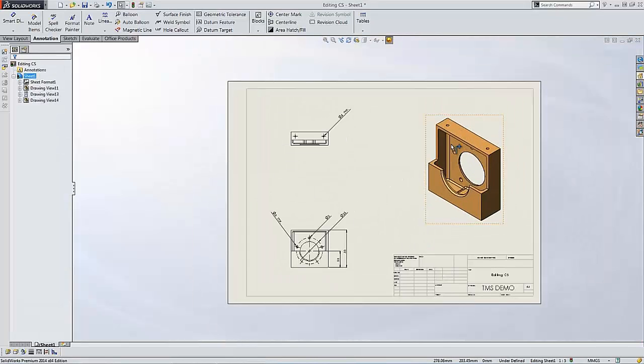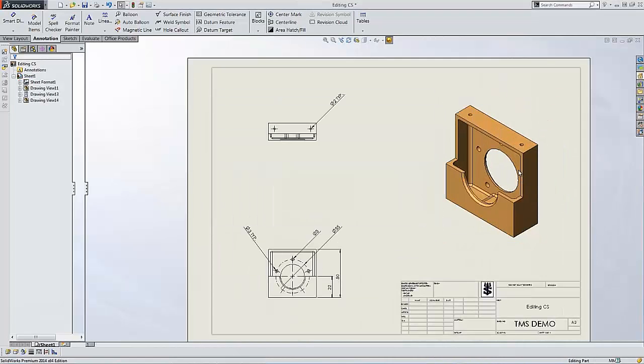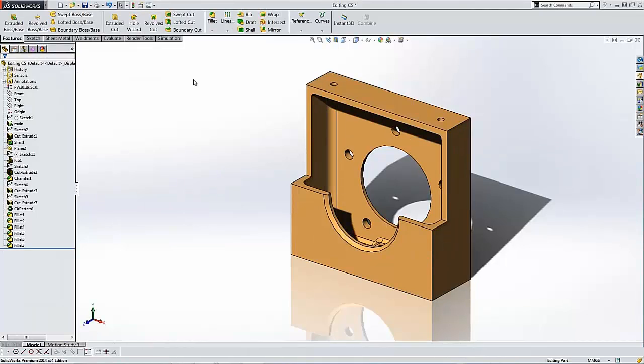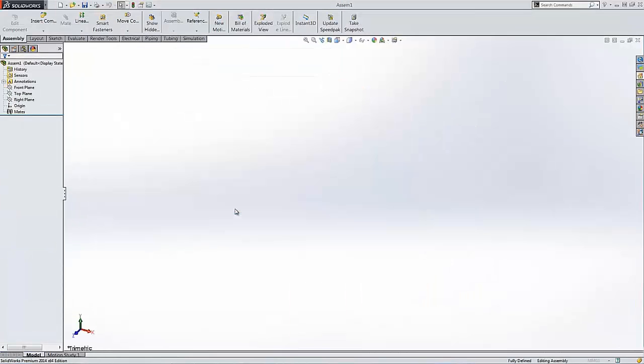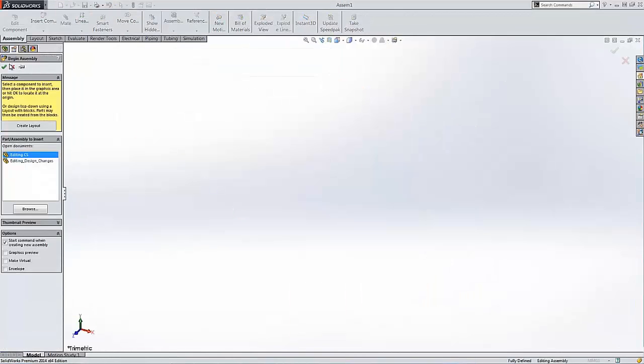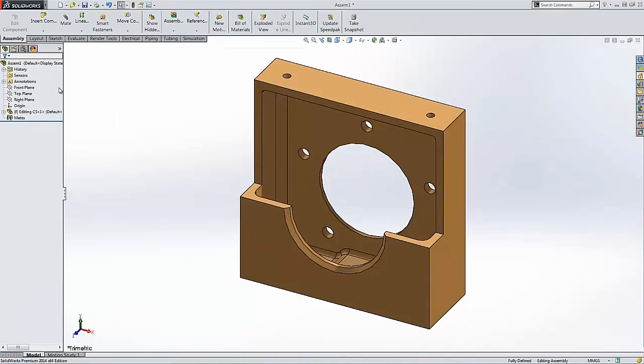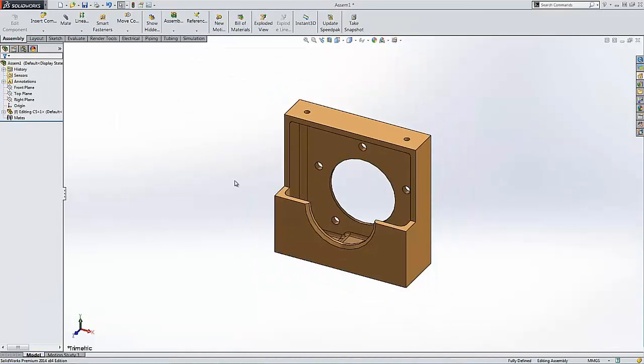Now we're at 14 minutes here, guys, and still shy of 15 tips, so let me create a quick assembly so I can keep my word to you guys. Now, adding additional components to an assembly, how do you go about it? Now, as we know, there's loads of ways. You can go via Windows Explorer, you can use the Insert Component dialog, you can use, I don't know, the tab on the right-hand side as your SolidWorks File Explorer.